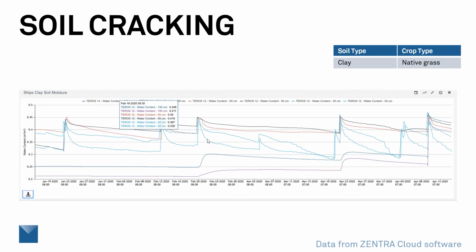If your water contents are going down much faster than you thought in your fine texture soil, you may have cracking around the sensors, and it's an important time to go out and look and see what's going on, and maybe try to do a better job of installation.